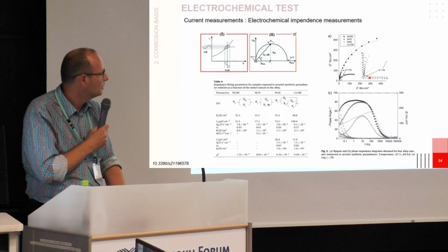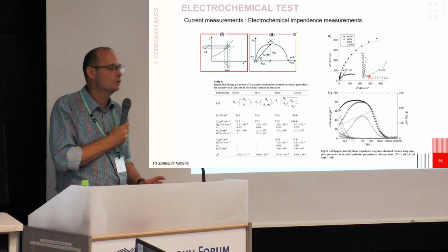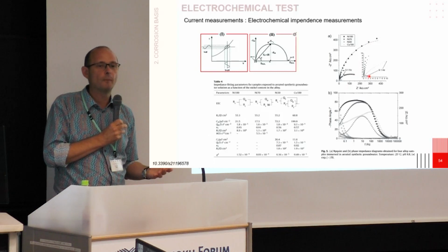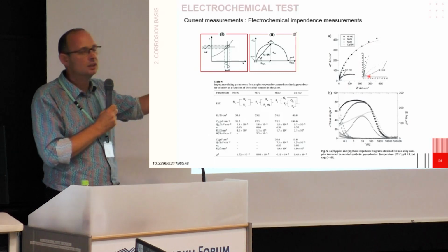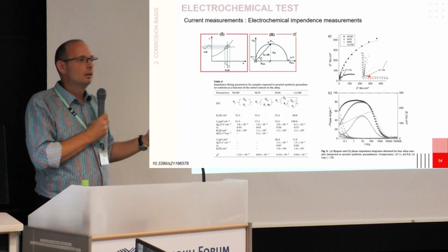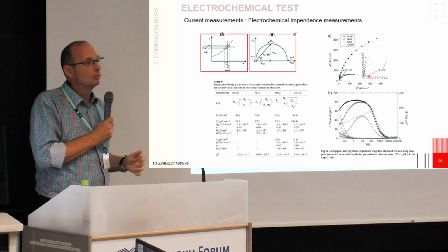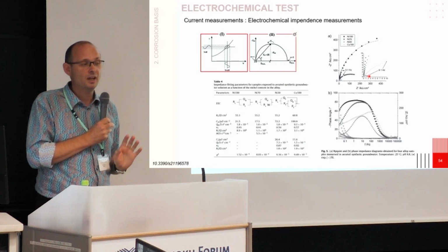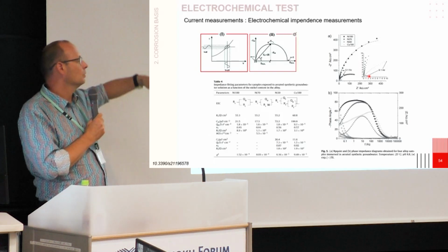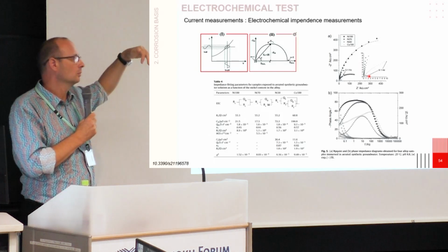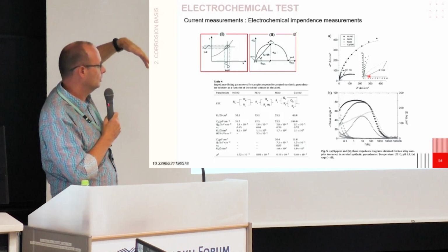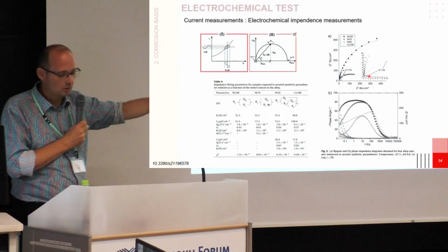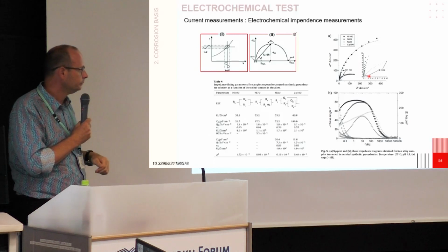And here you have the other alloys, which contain more copper. So you can see that the loop strongly decreases. If the loop is decreasing, that means the corrosion resistance of the material is decreasing. Sounds correct. If you have the possibility, you will see before the graph of OCP, and we were saying that, okay, the OCP of the copper is decreasing.